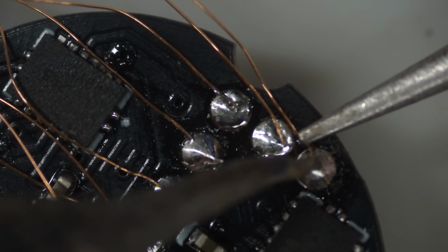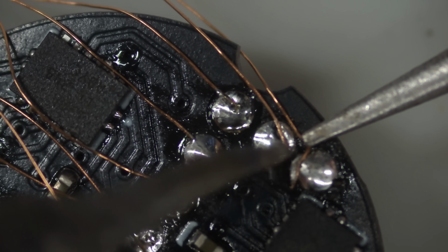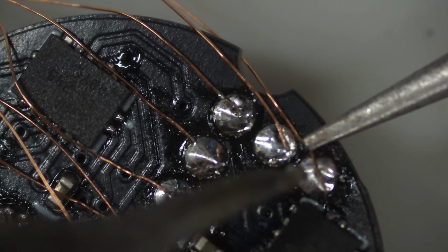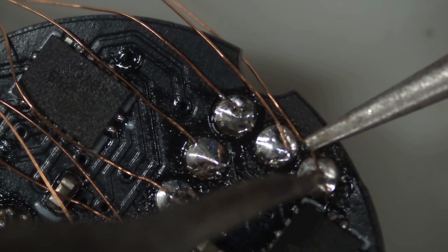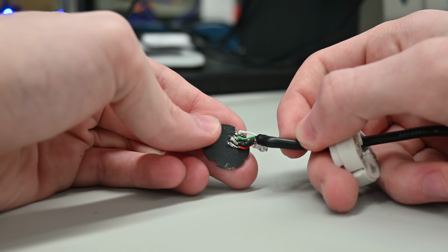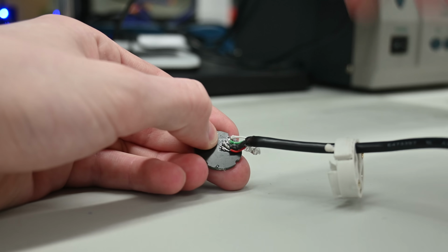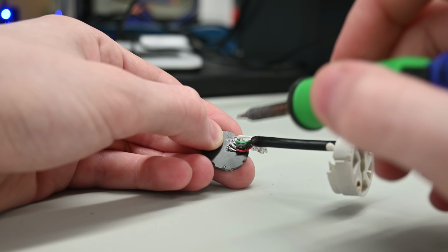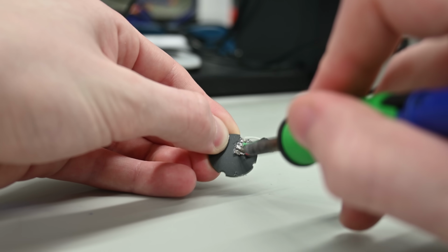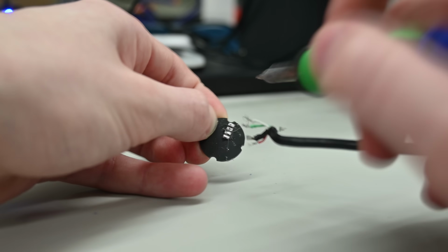I spent many hours looking at the PCB under the microscope, trying to find bad solder joints, resoldering components, checking values, and even completely replacing the microcontroller. Despite any soldering issues, the main problem I encountered was staring me in the face the whole time. I'd somehow accidentally mixed up my data plus and data minus pins on the motherboard, so USB was obviously not working. Luckily though, this did not require reordering the PCBs, as I could just swap around the connections on the custom USB cable I made.